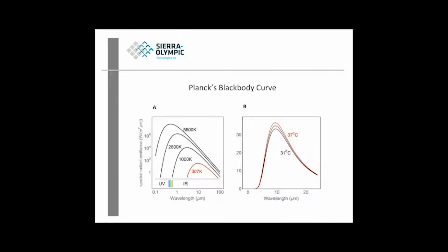An important issue to take away from here is contrast. Contrast is the derivative of this curve, meaning dQ/d wavelength, and the long wavelength has less contrast per unit change in temperature versus the midwave, which has a contrast advantage because it's on that sloping part of the curve.